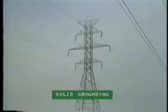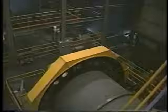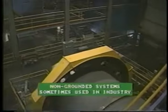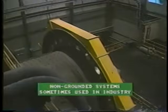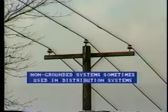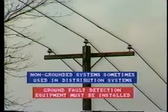Now, at this point, let's briefly summarize the methods of grounding which you will encounter. Solid grounding. This is the case with most utility systems above 40 kV. Generators may be grounded through an impedance so as to limit the magnitude of fault current. Non-grounded systems are sometimes used in industry where a continuous power supply is required. Distribution systems are sometimes not grounded, and in this case, ground fault detection equipment must be installed.